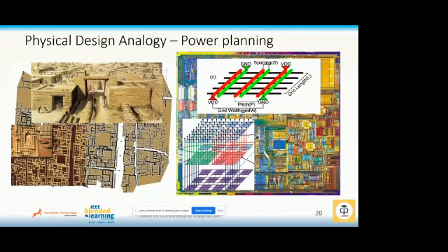So if you look at an SOC scenario, you would have designed all the different voltage regions and power islands, and there are many complications when you come up with a power plan, especially when you're talking about a low power design for a mobile kind of application. You have to take all the parameters into consideration when you are designing a grid.